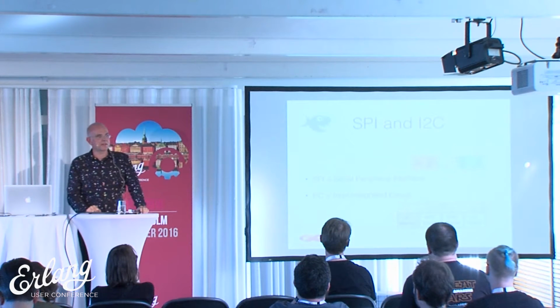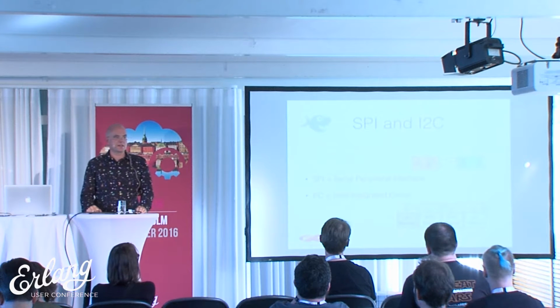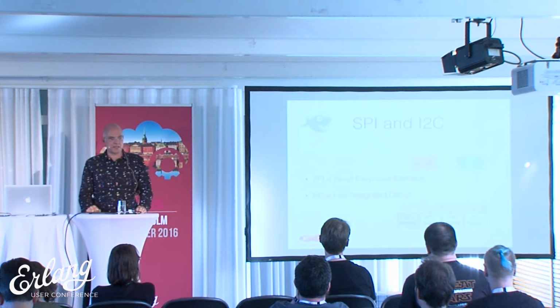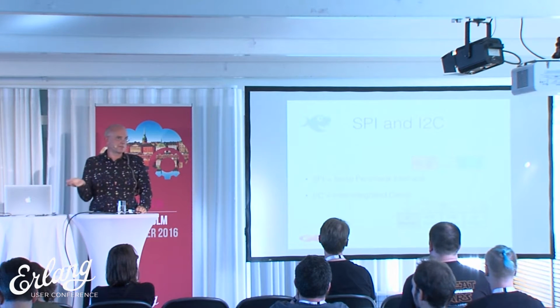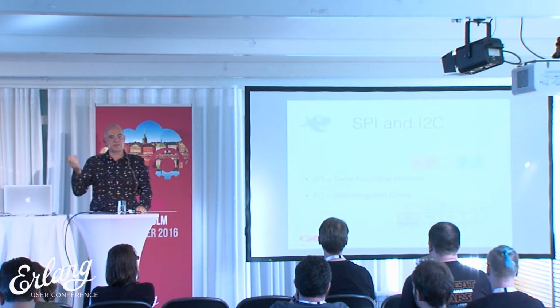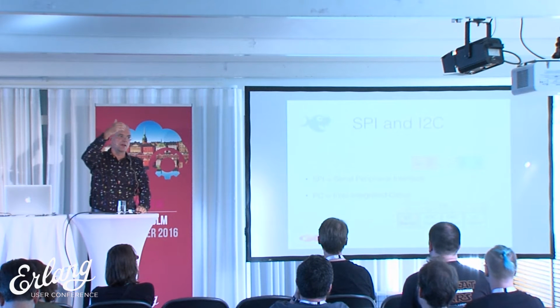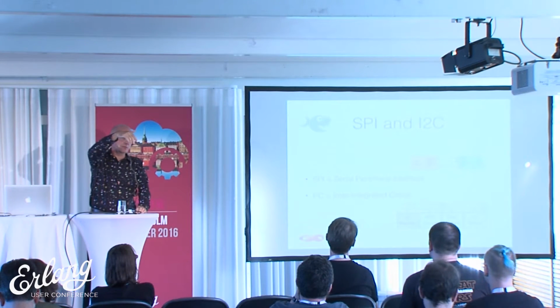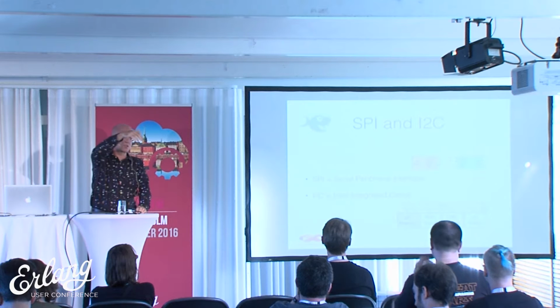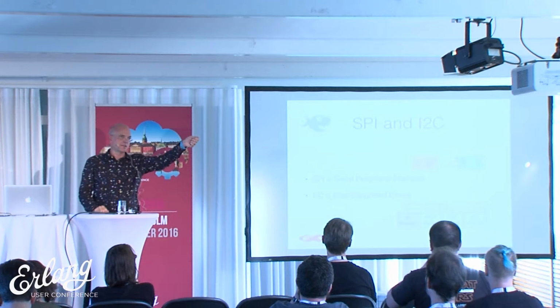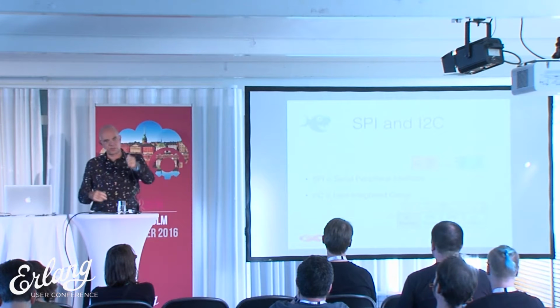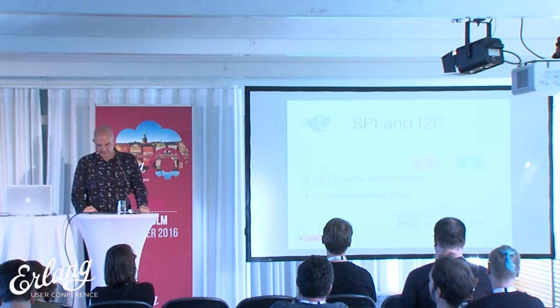There's also a 4th line, the chip select, which tells the chip that now comes some data, and it's for you. This makes it possible to share SPI with several chips. So for example, if you have lots of SPI devices, you could add GPIO and use the additional I/O lines as chip selects, and then drive this manually and basically say this chip, and then you send the data, and then that chip, and then send the data, etc.